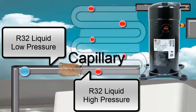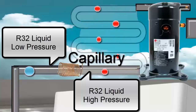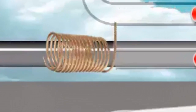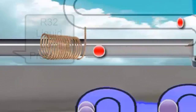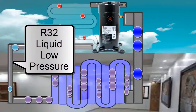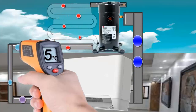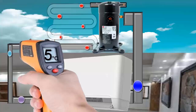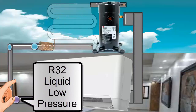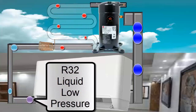Before returning to the premises to restart the cycle, the R32 must pass through the capillary tube. The capillary tube reduces the pressure of the R32 and, therefore, its temperature, returning the temperature to the value of 5 degrees Celsius. The R32 at low pressure and temperature returns to the evaporator unit to start a new cycle of heat absorption.